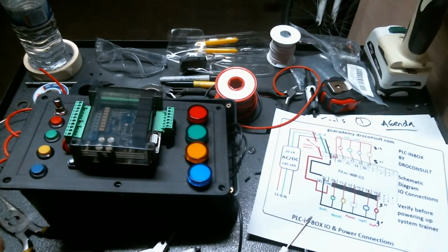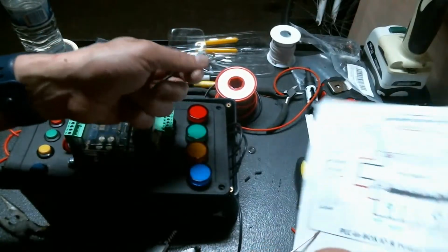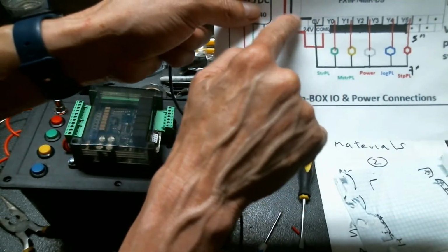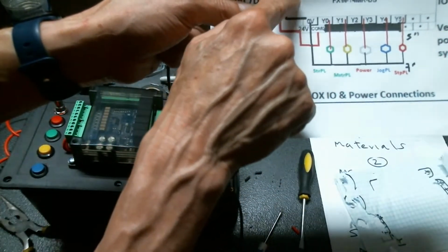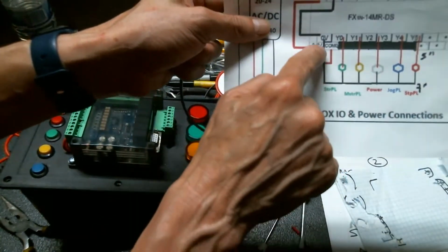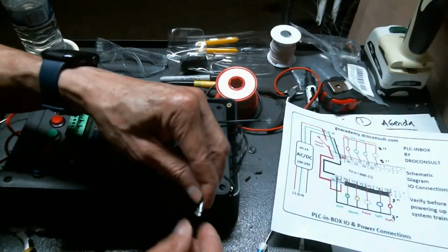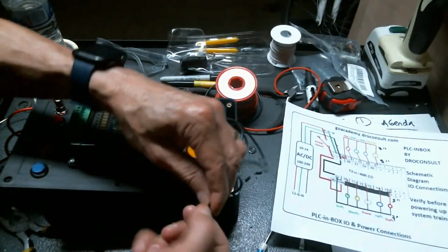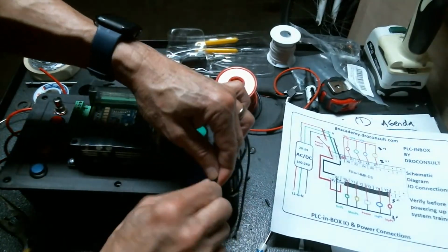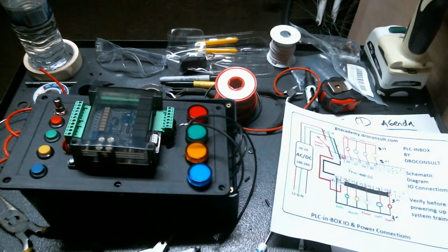We need to speed up the process a little bit. So what I'm doing now is taking this wire and uniting it with this wire that's going to go here, which is going to be united with the incoming wire. I'm looping this and this and this. So I'm going to loop it here. Okay, and I think I have some wire nuts. Oh, where are you, wire nuts? So I'm going to use a wire nut for that purpose.